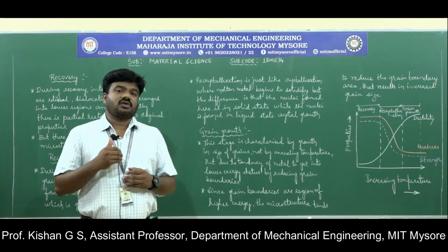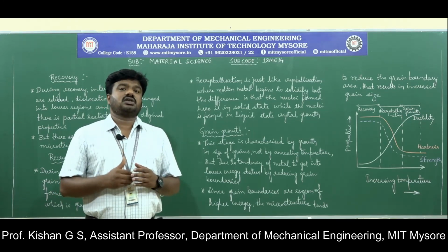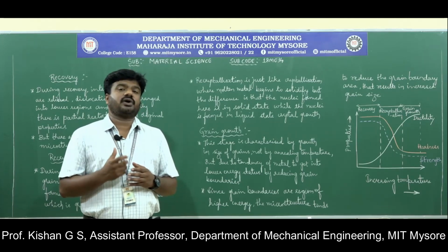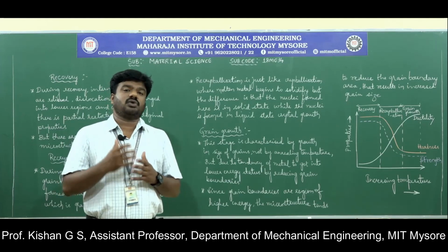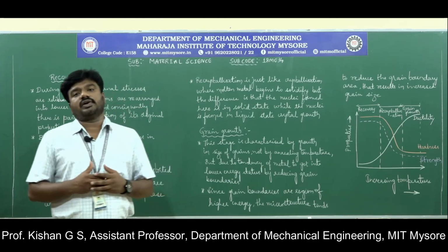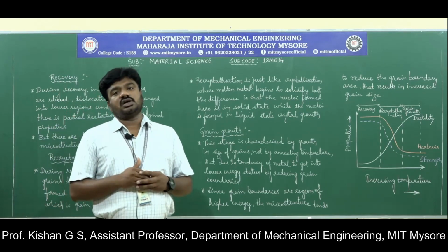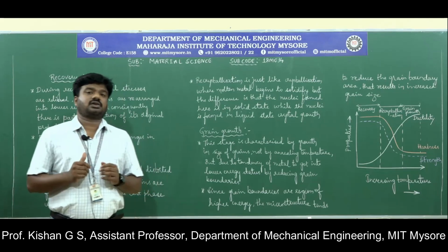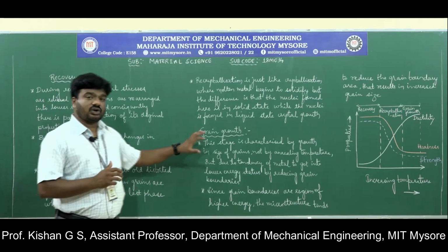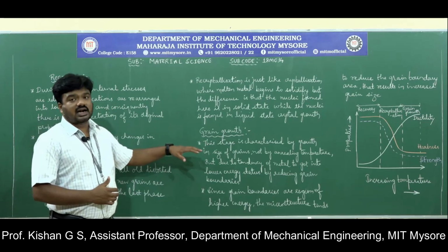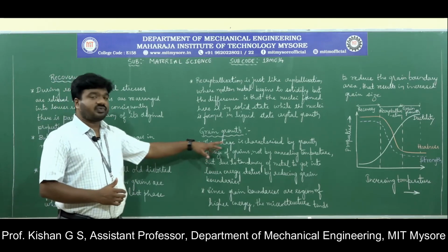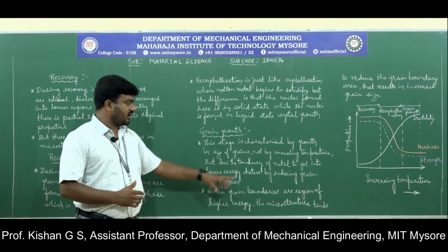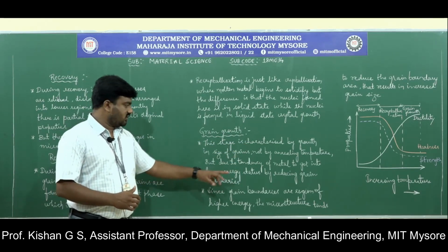So here, instead of the consideration of metal, there is always one particular point: the molecules or the atoms in the metal always tend to move towards their lower energy barrier. Thereby we consider in that perspective the concept of grain growth. So this stage is characterized by the growth in size of grains and not by annealing temperature, but due to the tendency of the metal to get into a lower energy status by reducing the grain boundaries.